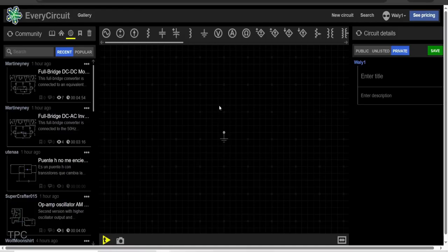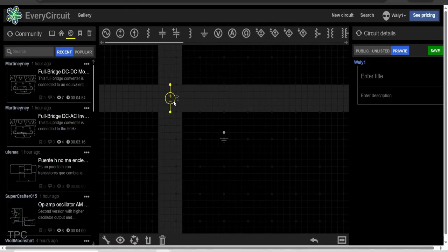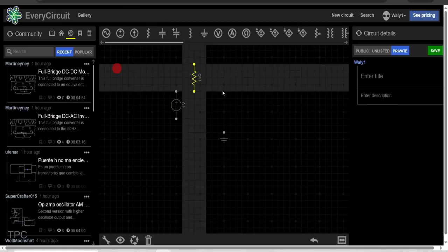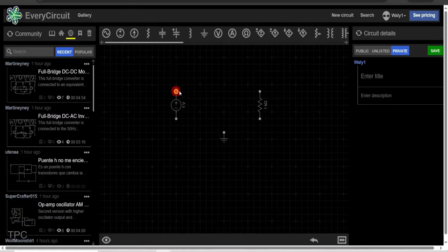Once logged in, you will see the central workspace, where you can build your circuits. Just above this workspace is a horizontal menu bar containing basic circuit components and sources. Simply click on a component, and it will appear in the workspace. To connect the components, just click the end terminals of 2 elements, and they will be linked automatically by a wire.